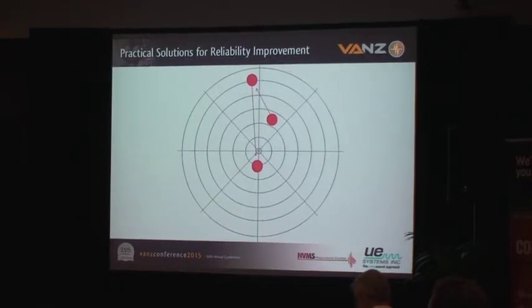The point of all this, change is bad. I don't care if vibration goes up. I don't care if it goes down. And there are so few people that I deal with or have dealt with over the years that even consider using below alarms. Everybody looks at above alarms. Not many people look at below.